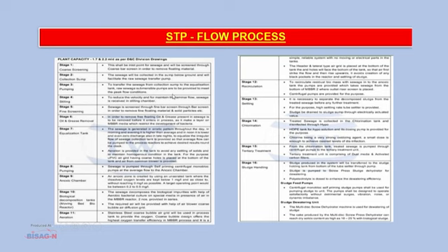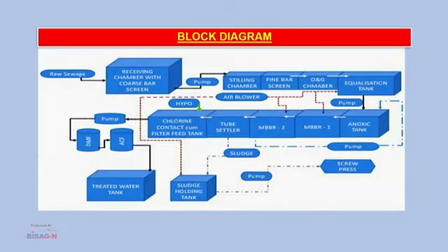submersible pump. First, the raw sewage comes to the receiving chamber. That's stage 1. There's a coarse screening placed in the receiving chamber. This shall be the inlet point of sewage and will be screened through a coarse bar screen in order to remove floating material.